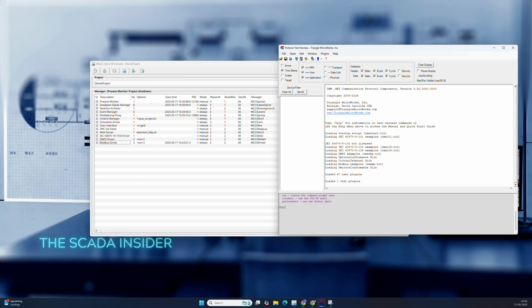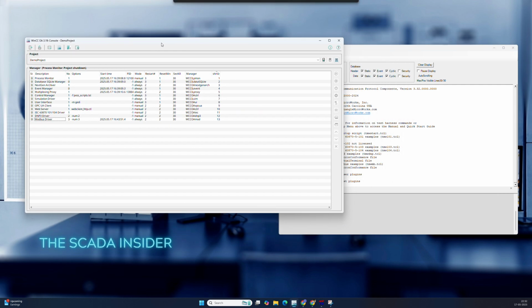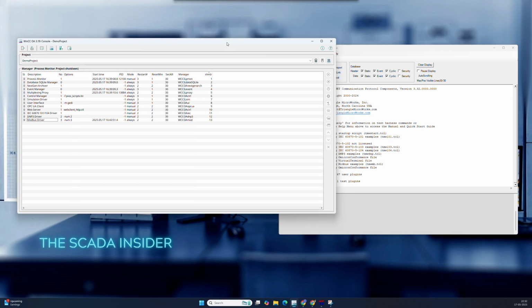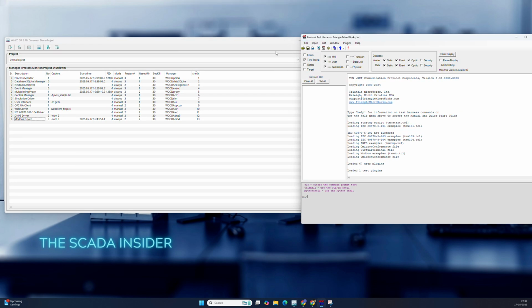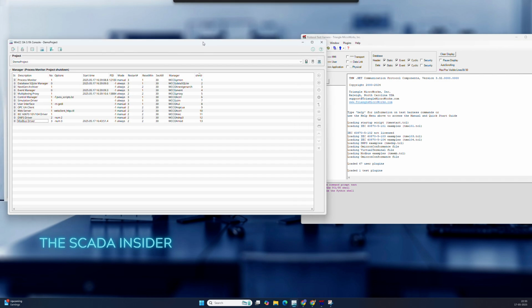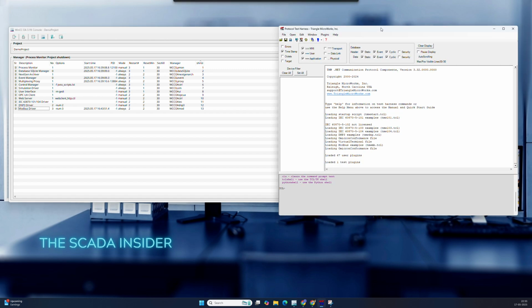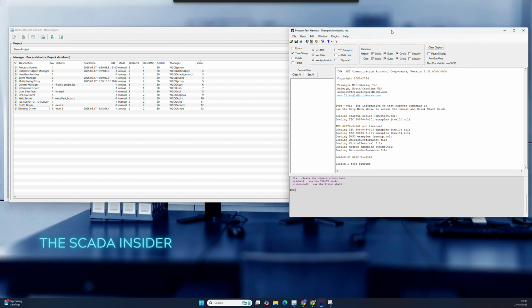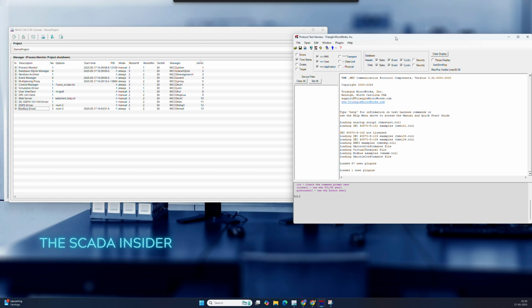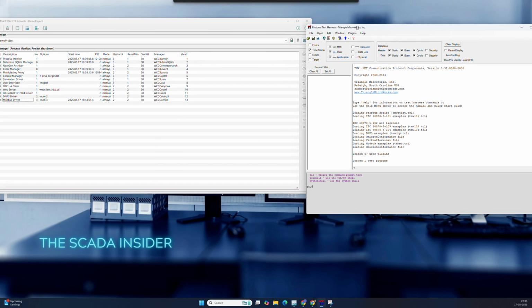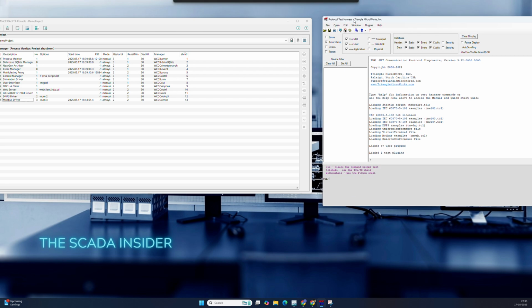Okay. So what is Modbus? It is basically a communication protocol. It was developed by a company called Modicon in 1979. It is used for communication between devices like PLCs, sensors, meters, SCADA systems, and all. It is a request and response protocol where the SCADA system acts as a master. It requests data from the slave. In this case, the slave device may be a PLC, any kind of meter, sensor, or other device. So SCADA is the master, and the other device which sends data acts as a slave device.